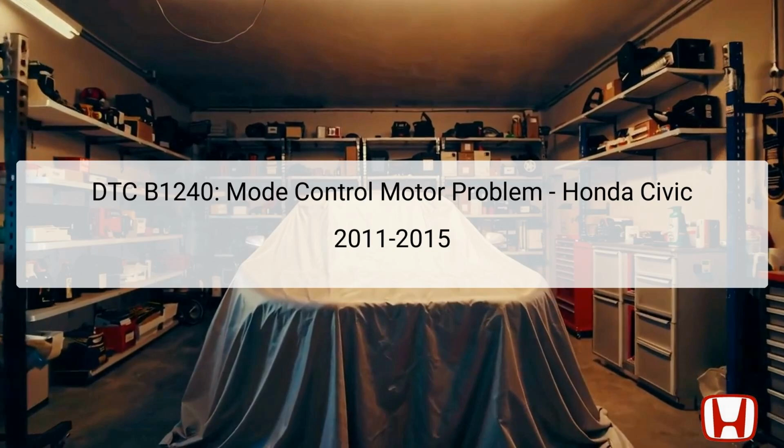DTC B1240 is associated with an issue in the mode control motor circuit, which is crucial for the operation of the vehicle's climate control system. It specifically indicates a problem within the circuit, linkage, doors, or the motor itself. Located in the dashboard area, the mode control motor's primary function is to direct airflow through various vents within the cabin, providing optimal thermal comfort to passengers.